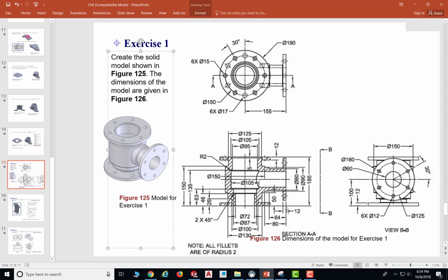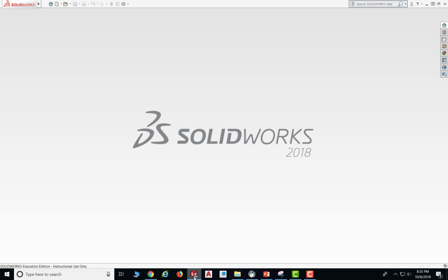then you make a new surface, reference geometry, the surface, then you extrude, then draw another circle, then extrude, another circle, extrude, another circle, then extrude up to the surface. So these are the steps, and now I'm going to show you a tutorial of how to make the part. So first of all, let's go to SolidWorks and create a new one.